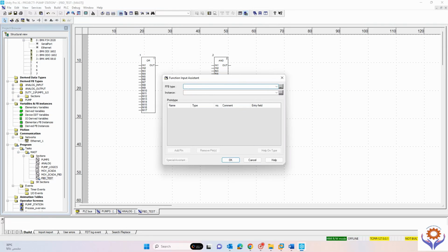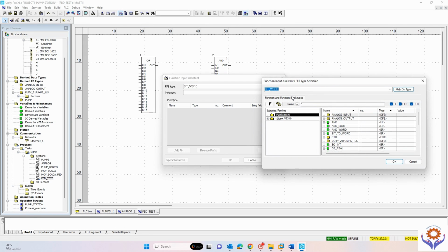If I type now some different example, like bit to word. See, if I don't know how to make it, just check here. Actually I need to add BIT_TO_WORD. So it's not appearing. See here, I will show you. In the library set, you can browse down, like a bit. See, add.